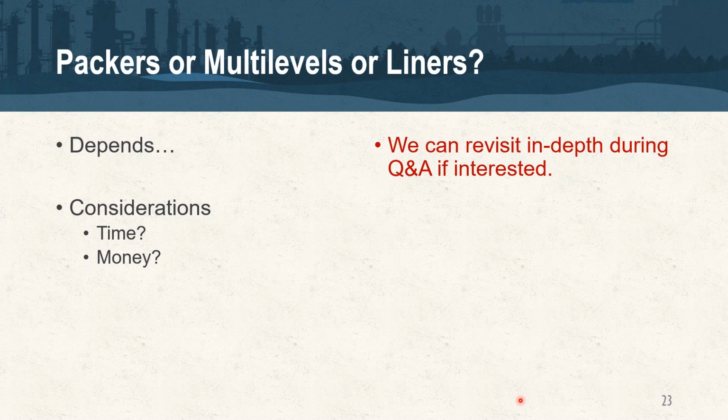But again, going back to what we talked about at the very outset, when it comes down to the injection program at a site, at the end of the day, we need an open borehole, whether it has these tools in them or not. If they are in there, they need to be removed for injection and then be replaced. And that can be fairly simple to do for some of them. It can be very complex to do, very time consuming. But again, those are all decisions that, if you're going to use those as part of your program, have to be considered heading into the RDC process, because it affects how many boreholes you're going to drill on site.